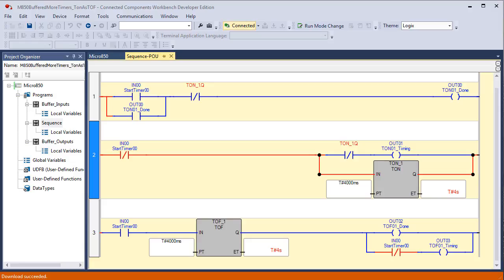And for the done bit, we had to say that it wasn't done. So if you look at the very first rung, turn on input 0. If it's not done, then it's done. That's the behavior of an RSLogix timer data type. For a TOF, when it's not done, it's done. Then when it is done, it's not done anymore.